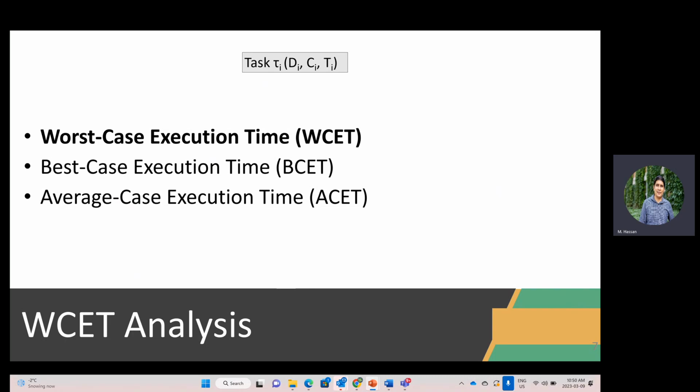It depends on so many things. What is the status of the operating system? What scheduler is being deployed, which is not real time? How many other applications are competing with you? What is the power status of the laptop? All of these things create a huge amount of variability that is not good for real time. So if you design your system for average performance, it hurts a lot the worst case execution time. It hurts analyzability, which is not good for embedded systems.